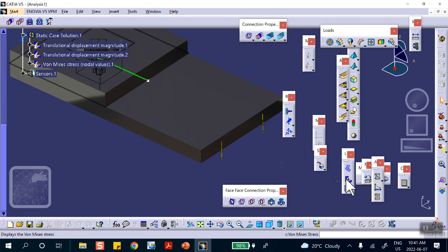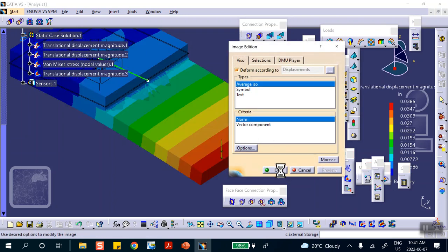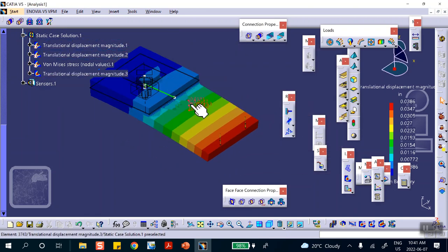So now we look at, for example, let's look at the deflection. There we are. All this garbage element is also showing here. These are contact elements. But anyway, you can see the other problem that I did, you probably didn't pay attention to the numbers. Although numbers are not reliable, it was almost zero deflection for the maximum deflection. But here you can see that you have a 0.03 deflection. And these are tied together with that compression force of 50 pounds. Okay. Any questions here?